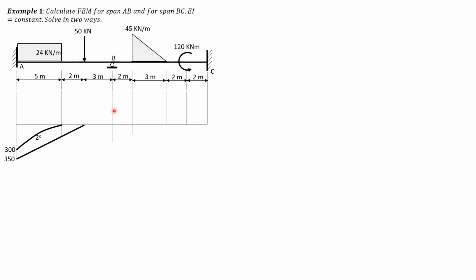Then due to the fixed moment at B, I'll just call that MB, but it's really the fixed moment at the far end, B, rectangle. I assume it positive just like before, so that whatever the final value is, that's the final answer also. And due to the reaction at B, we have RB times 10, the span is 10, so 10 RB over EI supposedly, but EI is treated as 1.